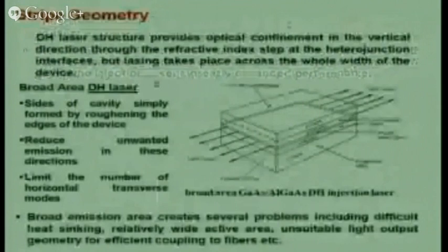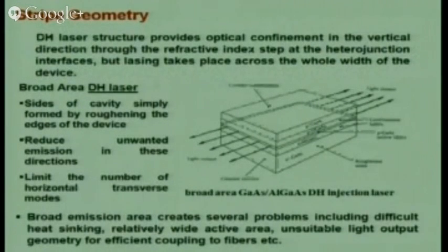So double heterostructures: an injection laser diode fabricated from lattice matched III-V alloys. Optical confinement on both sides of the PN junction gives the injection laser a greatly enhanced performance. So again, the same structures, but we need two mirrors at the ends so that the stimulated emission overpowers the spontaneous absorption. So we have a P-type aluminum gallium arsenide, we have N-type aluminum gallium arsenide, and we have P-type gallium arsenide, which has a low refractive index profile and is the active region.